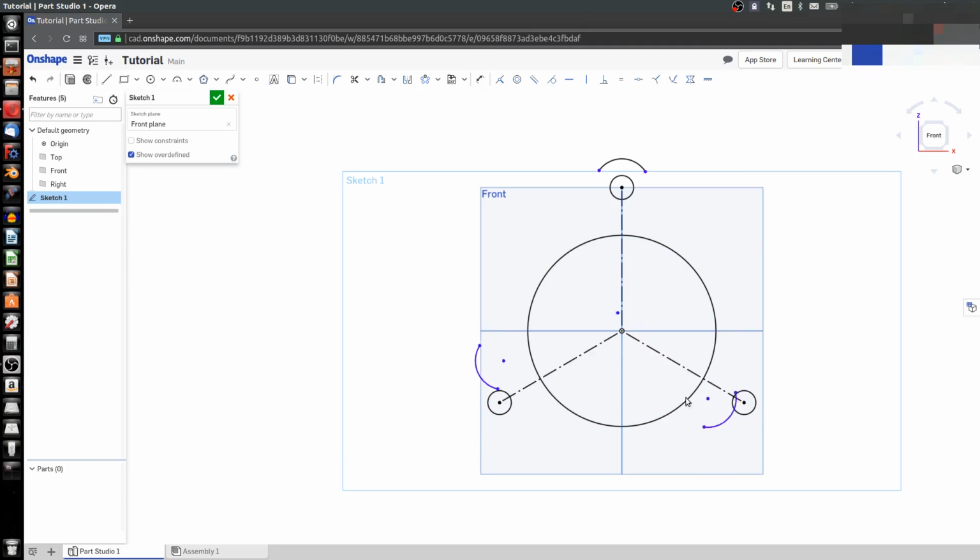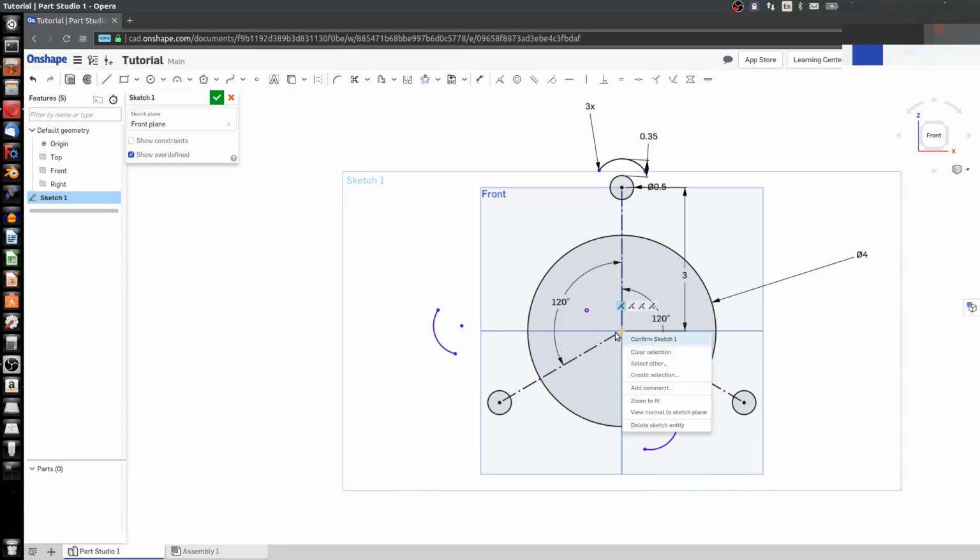Notice I have a center, almost like an arc center of my pattern, and I want to make sure that my center is with the center of whatever I want to revolve around. In this case, I want to revolve around this circle, and so I click, and I choose coincident. From here, I can add in the relations of concentric. And the other one, because it has a pattern constraint, knows where to go when I position this one.